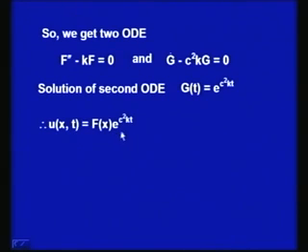So, it is not of any practical importance if I take k to be positive or k to be 0, because at k equal to 0 it would depend only on x and not on t, and again that would not be of any physical significance. So, we have to take this k as negative, only then would it have any practical significance for the flow of heat.